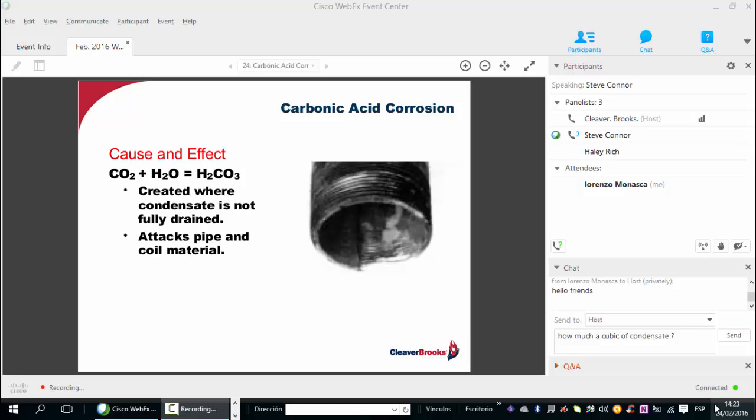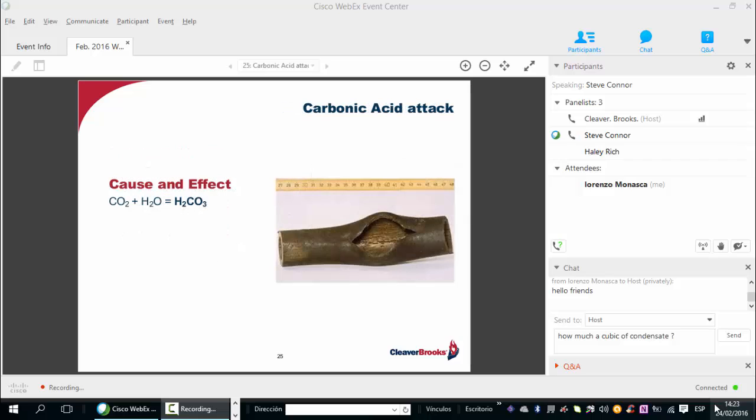It's pretty nasty stuff, which silently eats away at the return piping, attacking the weakest portions of the piping first, like the threaded connections, but then also causing wall thinning by forming grooves, as you see in this picture now. And this weakening can also lead to extreme cases where you have a high-pressure condensate return line, and it's precipitating actual splitting of the pipe wall, causing not only a major safety issue, but a significant loss of energy to wasted condensate and, of course, a stop in production.